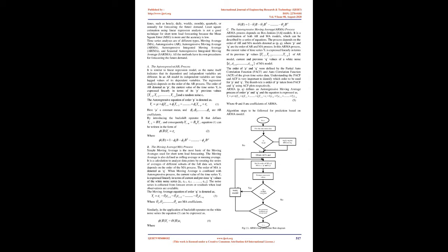Time series methods are based on the assumption that the data have an internal structure, such as autocorrelation, trend, or seasonal variation. Moving average, autoregressive moving average, ARMA, and Kalman Filter techniques are used to predict and estimate the load too. According to [3], medium-term forecast of 4 to 10 years is highly essential for planning the size of power plants, construction and installation of the equipment in power plants, and for the addition of new transmission and distribution facilities.